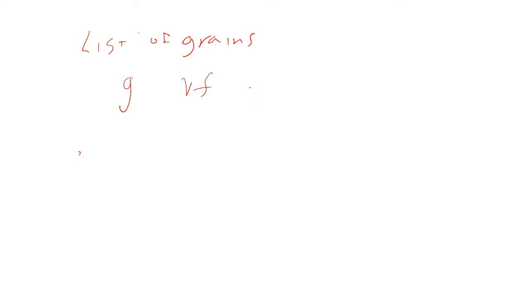So that you know what slip systems, what deformation modes will be active, right? And you can set that however you want, right? There's a properties file. You can tell it, I don't want you to use basal slip in this HCP material.